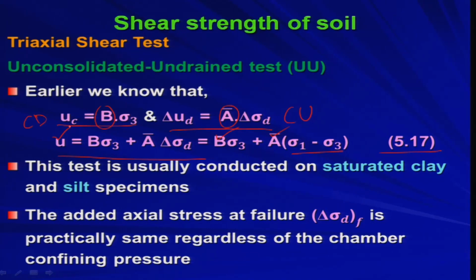This test is usually conducted on saturated clay and sealed specimens. Generally, for saturated clay and sealed specimens, this UU test is conducted. The added axial stress at failure, that is Δσ_dF, is practically the same regardless of the chamber confining pressure. So we will see that.